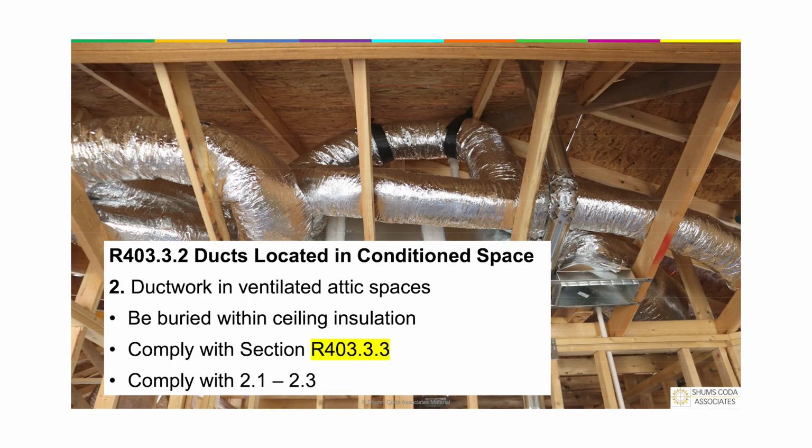All right, so number 2 in that list. Number 1 was if it's inside the thermal envelope. Number 2 is if you happen to bury the insulation inside the ceiling, complying with R403.3.3, and you also have to comply with 2.1 through 2.2.